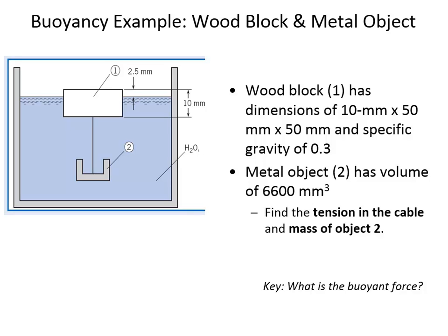Force due to buoyancy is equal to the volume displaced multiplied by the unit weight of water. Now, this is an easy place to make a mistake. We have a unit weight of the block, but the buoyant force is independent of what the block is made out of. The force of the water pushing on the block is unaffected by if the block is made out of wood or plastic or metal. The buoyant force depends on whatever fluid is displaced. In this case, the fluid is water.